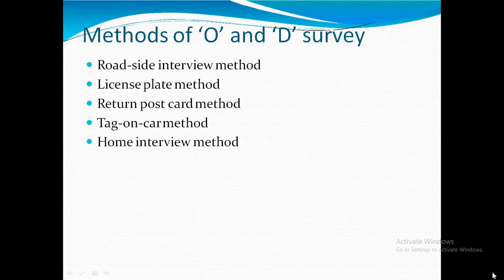Each party at the observation station is given synchronized timepieces and they note the license plate numbers of the vehicles entering and leaving the cordoned area in the chit. This method is quite easy and quick as far as the field work is concerned. The field organization can also be trained quickly. This method, however, involves a lot of office computations in tracing the trips through a network of stations.